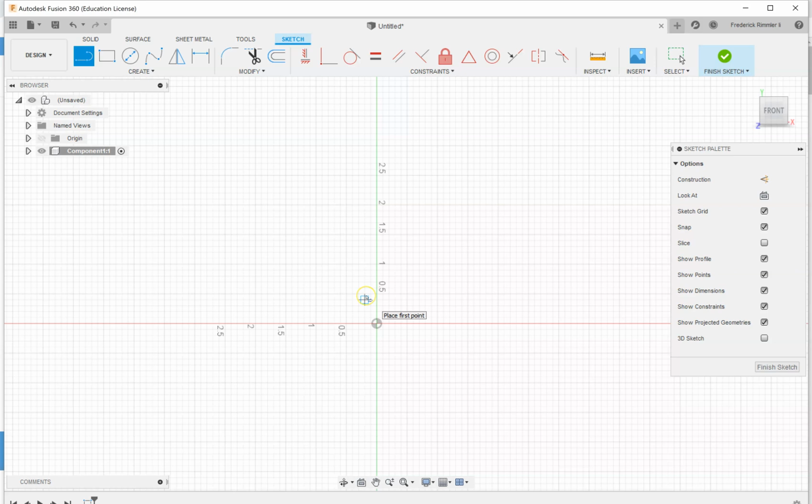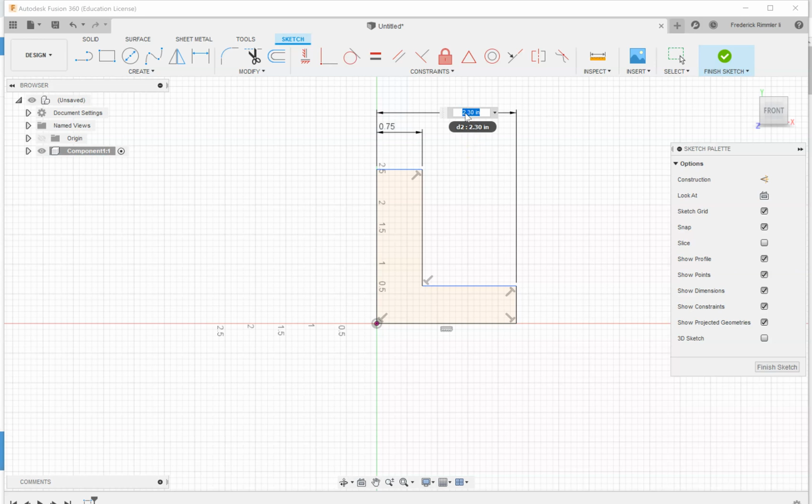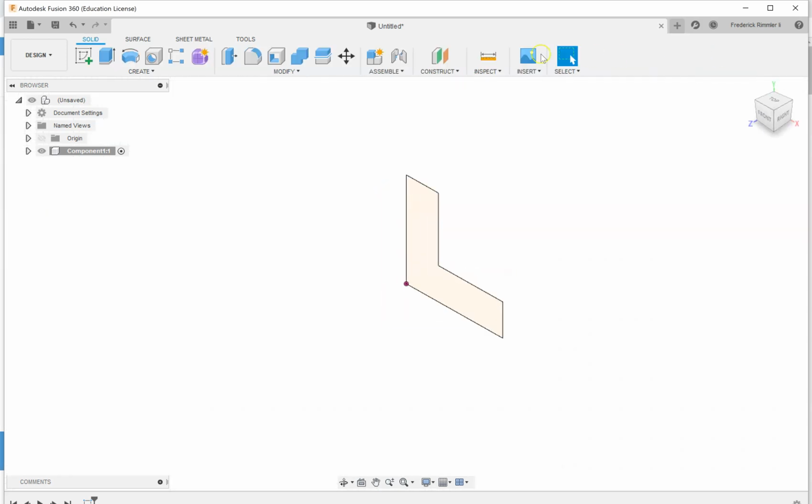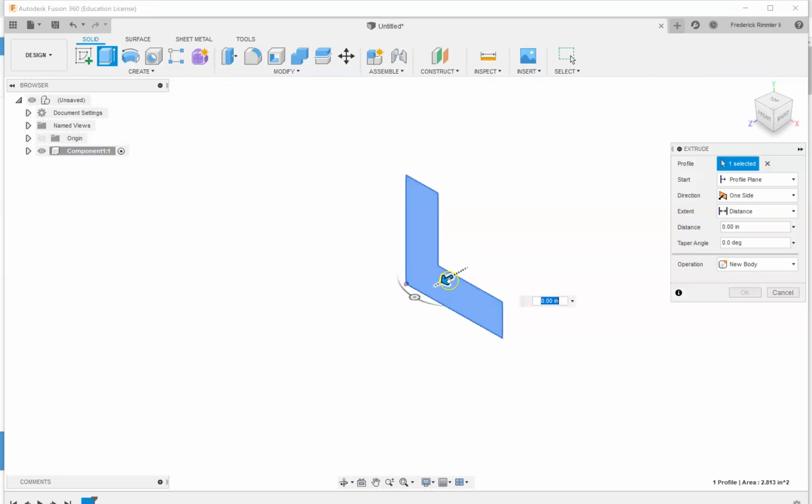And so to do this green piece, I'm going to lay the piece flat in front of me, and I'm going to start with this big L shape right here. Add my dimensions. Let's see, 0.75, and then it's 3 cubes across, so I'll make it 2.25, 0.75, and then 3 cubes tall, so I'll make it 2.25 inches. Finish, and press pull my first layer into 3D,